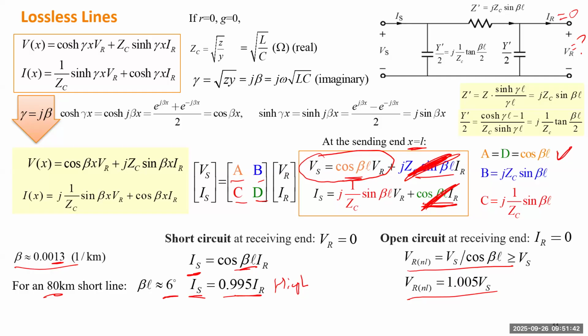Okay. So if you operate a short line, it's fine to open the circuit on the load. If you want to do any maintenance, it doesn't cause any impact to the generator or the source at all. But definitely, if you have a generator powering some load and you open the circuit, you also need to reschedule the generation of the generator to keep the power balance.